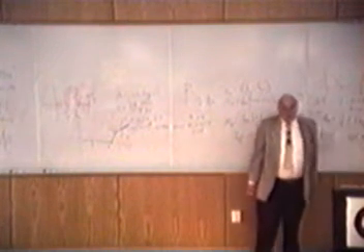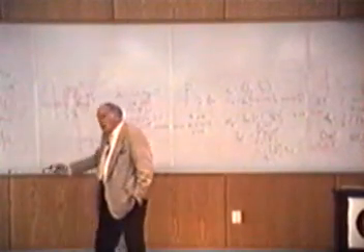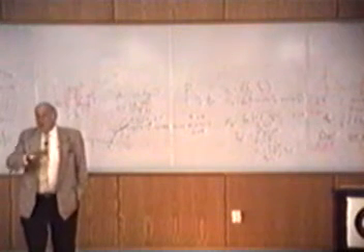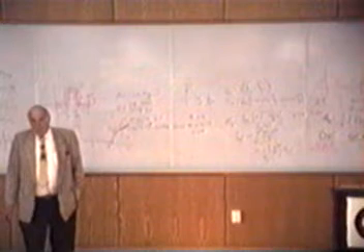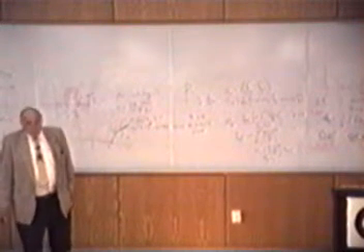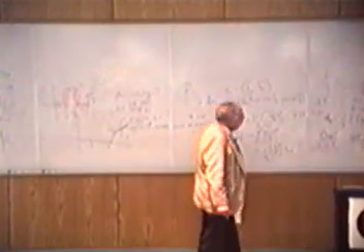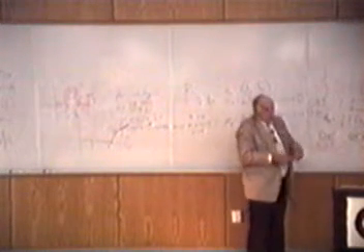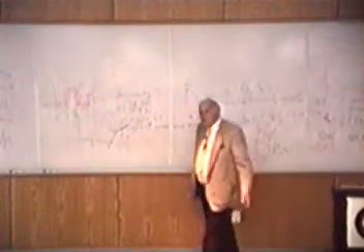And you can work out the formula very easily. What will you see for a sinusoid that is not harmonic? You'll find it's mainly spread around nearby, but it's spread over the whole spectrum. It isn't what you think it is. When you use a fast Fourier transform, you are asserting this function in this interval is periodic. Those choices you made there may have very little to do with the periodicity of the signal.